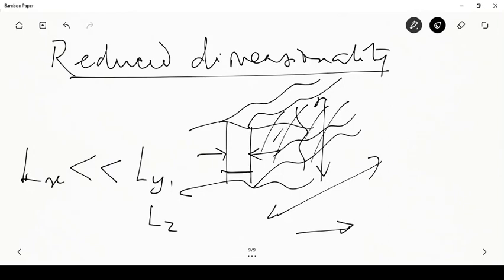So along the length and breadth of the wall, the variation in temperature would be very small. In the same way, the other side of the wall, exposed to the surroundings, would be exposed to the same ambient along its length and breadth, and therefore the thickness of the wall is the direction in which the maximum temperature change occurs, and the temperature gradients are the biggest there.